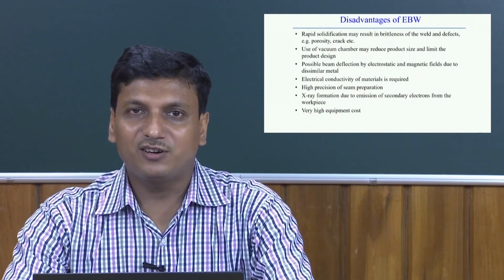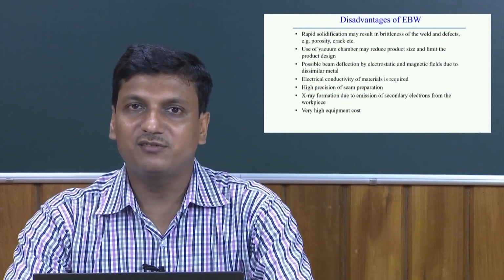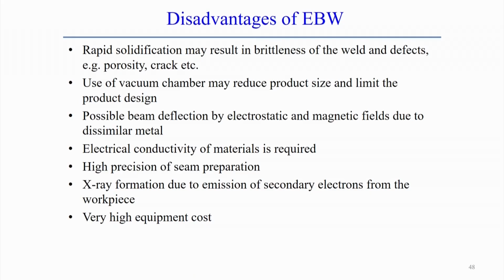First is, of course, high heat concentration. So, rapid solidification may happen, and this rapid solidification also produces a different type of structure, and finally in most cases it results in brittleness of the weld and several other defects. Porosity and cracks may form due to the rapid solidification. This is one disadvantage.